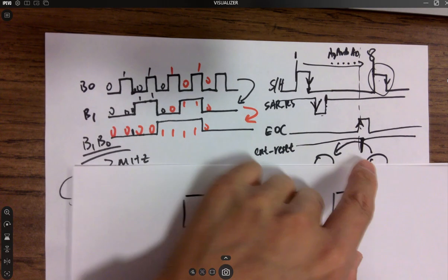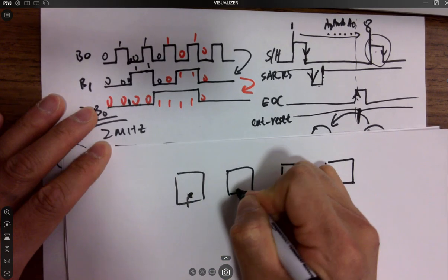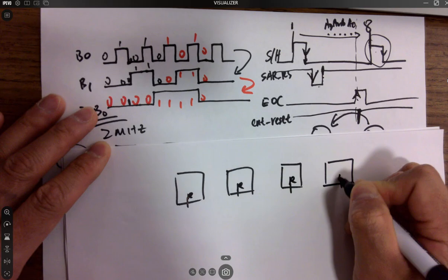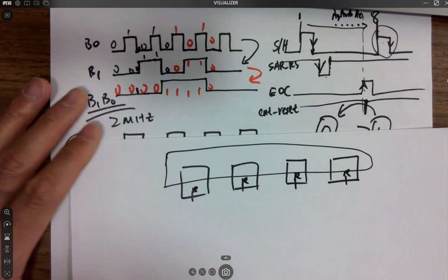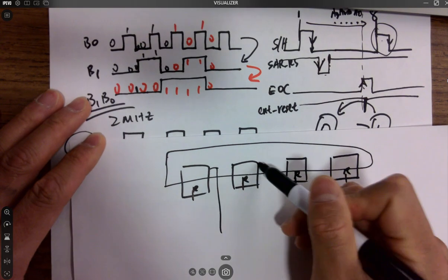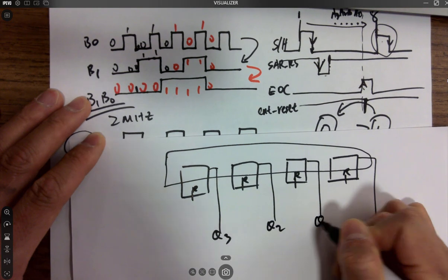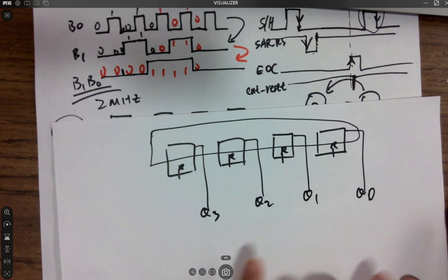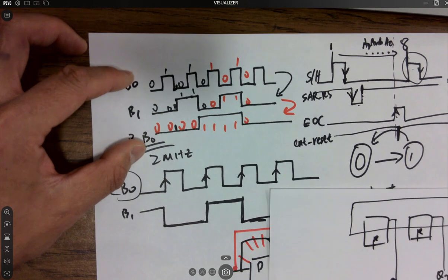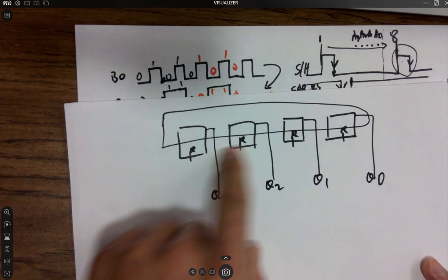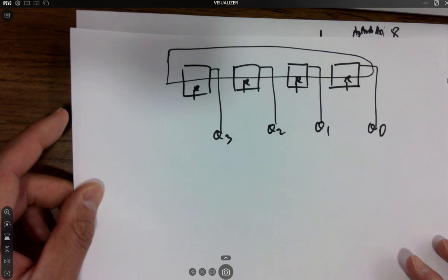And see, this is the dip, which makes sense because the reset is active 0. So whatever the counter circuit is inside, I'm not drawing them. The counters are outputting 4 digits, Q3, Q2, Q1, Q0. So these are the 4 bits. You align them like this, they're counting. Does that make sense? That's a counter's output, and that's a reset. So how would you like to design the circuit to force it to reset at number 8?